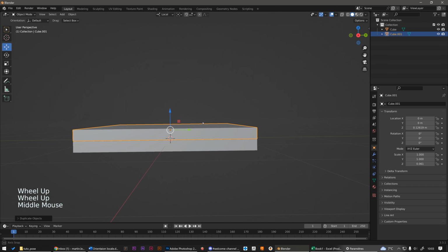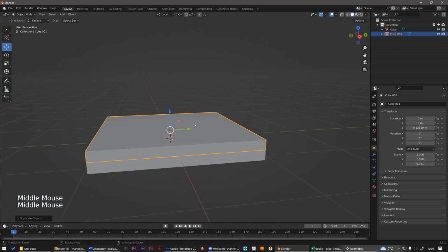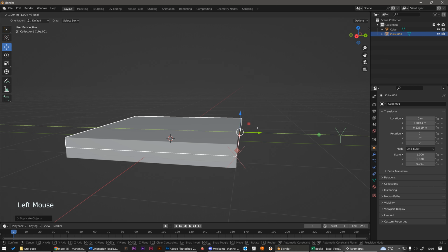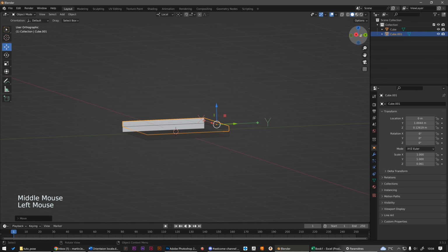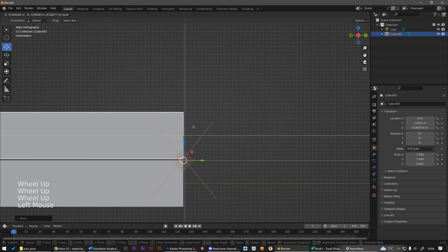Now I will move the origin of the screen to the hinge, so it will rotate around the hinge. So for that we can do as we have done so far. We go to Options, and we check Transform Affect Only Origins. So let's move the origin, but it's going to be more practical to use an orthographic projection and a side view to move the origin precisely at the hinge.